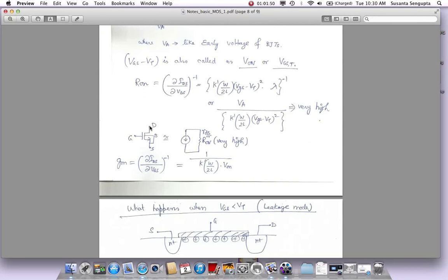So this is how the drain current gets affected by changing the drain to source voltage. But there is another term we will use later on. I thought I'd just put it here, called GM. GM is the same thing, but in a different way. Oh, I should not have this -1 here, sorry. I made a mistake here. So GM is a measure of how the drain current changes with respect to gate bias.